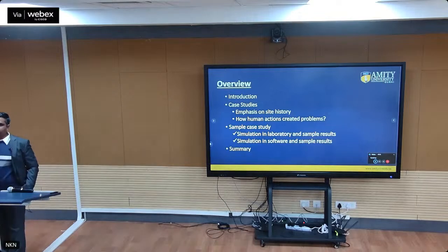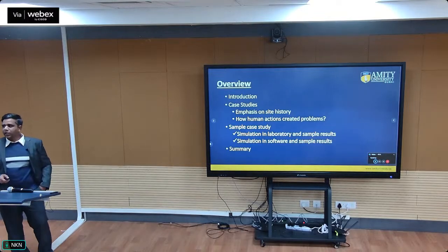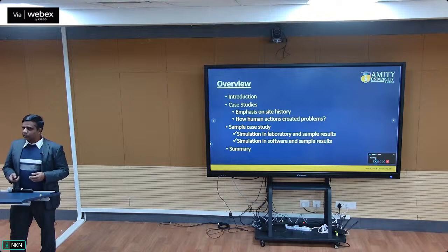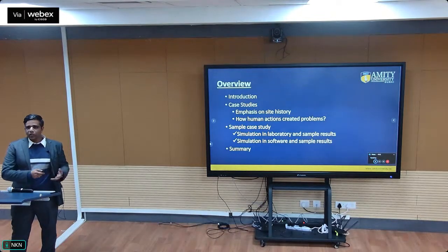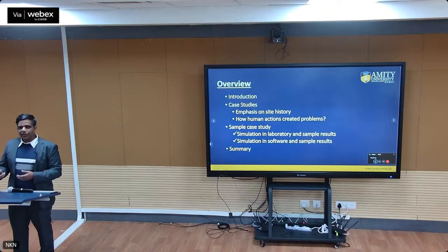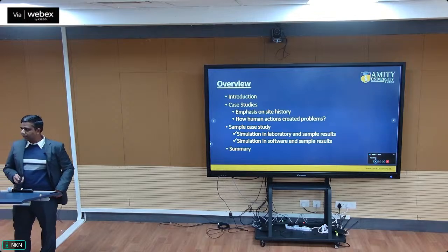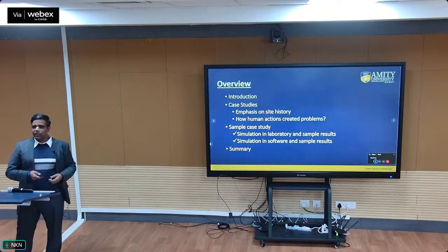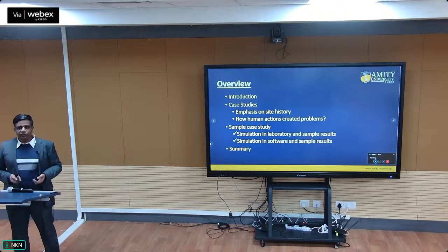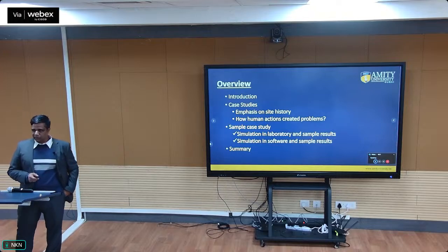In many countries, whenever we are constructing any infrastructure project, the consultants or the contractors will not have site history data, like what happened at that particular construction site in the last 25 years or 30 years or 40 years. Unknowingly, one day we start the project, the consultant designs, the contractor constructs. Later on, after 5 years or 6 years or 10 years down the line, we face some issues and go back to find what happened, where the problem is, and we identify that there was some site history in the past which was not considered. These are the kinds of cases we have found in our many forensic investigations.